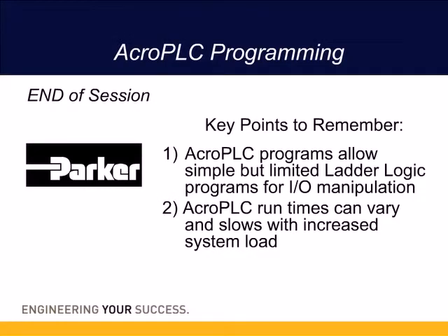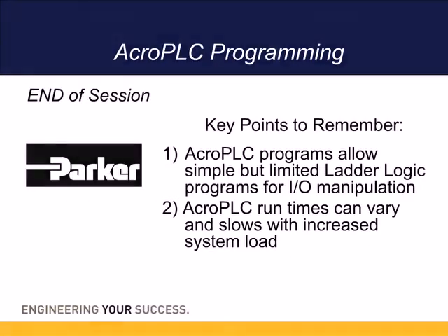This completes the AcroPLC online training. Key points to remember are that the AcroPLC programs allow simple but limited ladder logic programs for input-output manipulation. AcroPLC runtimes can vary and slows with increased system load. For more complex ladder programming, or for applications requiring a specific scan time for execution, use the newer 9600 PAC series controllers. Thank you for your time.